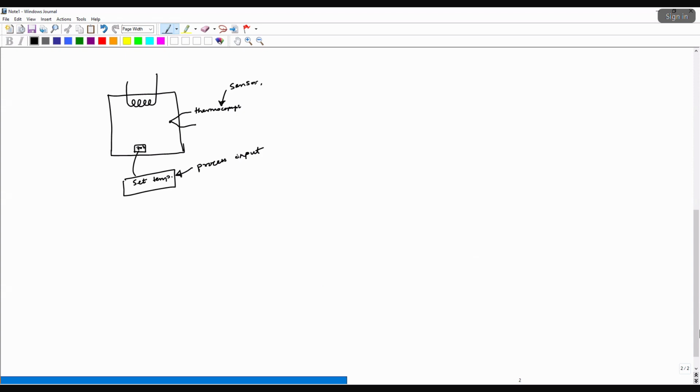and the thermocouple with the external circuit acts as the transducer, thermocouple plus the electrical circuit, because you need to have a circuit to record the EMF that develops when you have a temperature difference between the hot end and there will be a cold end somewhere. And so basically the circuit with the thermocouple together, they will form the transducer stage. And so you have a signal, right, an electrical signal, which is calibrated against the temperature, right?